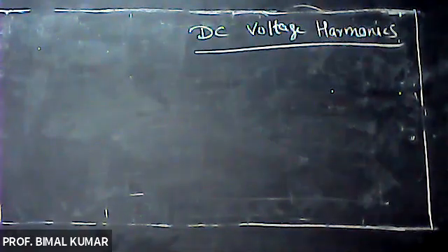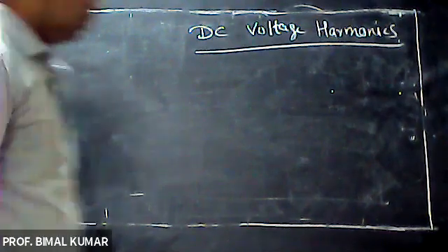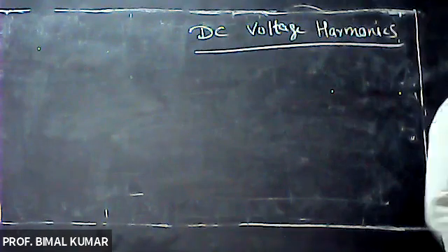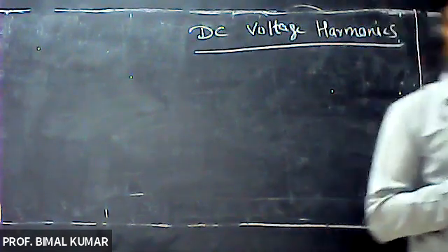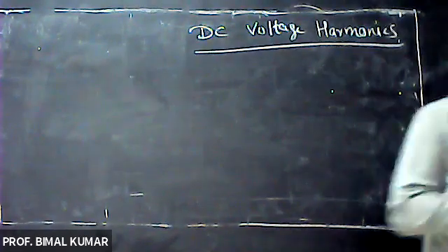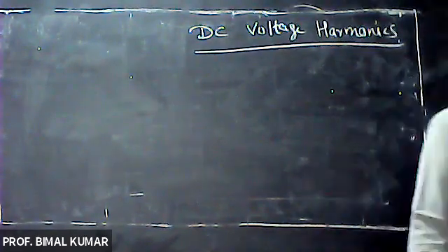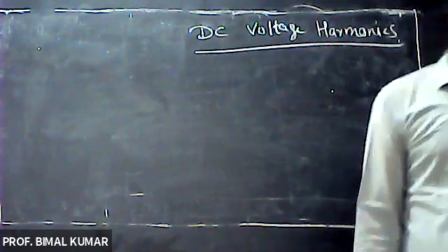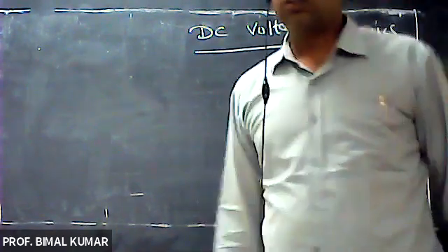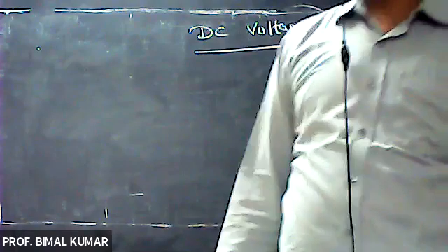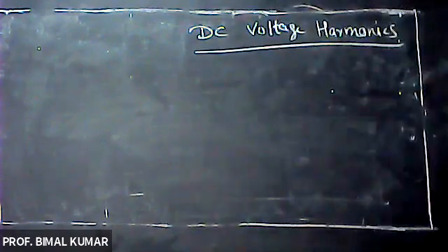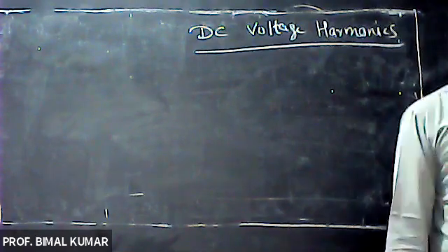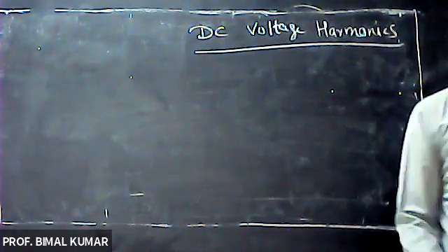Yes. So in that DC voltage waveform, in this bridge analysis, the DC voltage waveform contains a ripple whose fundamental frequency is 6 times the supply frequency, right?